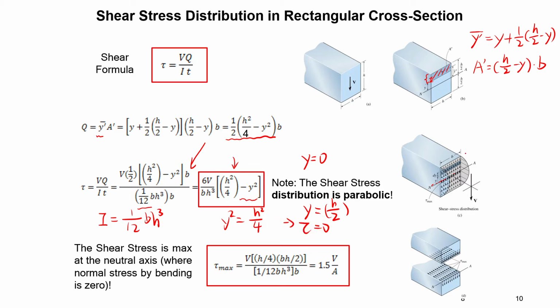Okay, so essentially that's the distribution we kind of visualize here. And here in that cross-section plane, we're just using different sizes of area to quantify the intensity of shear stress. Essentially, at the edge it is almost tiny, zero, and in the center you can see the area become larger. And to quantitatively show that, the equation is essentially this parabolic equation.